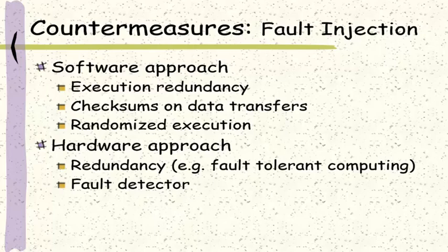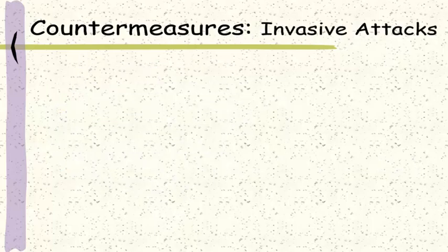Now we talk about some of the countermeasures to invasive attacks. Some of them may also be applicable to semi-invasive attacks. First, recall that attackers can probe at a single bus line to steal data. Almost all the data buses that connect the CPU and the memory are either in the increasing order from the 0th bit to the highest bit, or in the opposite order from the highest bit to bit 0. This makes it easy for the attackers to locate the bus line they want to probe.